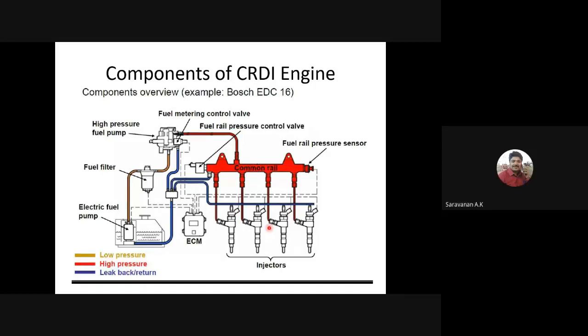Yes, sir. So that's the working of the various components present in a common rail injection system. Here the high pressure pump is mentioned as a supply pump, or a supply control pump. That is called the SCV, the supply control valve, as they mentioned. Then the fuel metering device, then the pressure control valve, then the fuel sensor. So like that they explained.